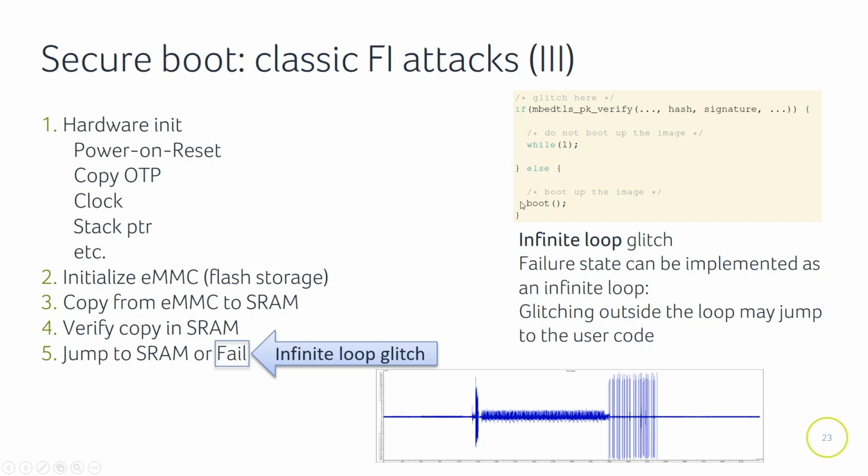We end up here. And the beauty of this attack, or this glitch, is basically that now we have infinite time. We can glitch anywhere because this is an infinite loop, so now we do not have any timing restriction. We can keep glitching, and as long as we manage to corrupt this endless while loop, we're done. We will end up in our booting code. So this is a classical attack, and it is something that has been haunting many secure boot implementations. We might still see one of these things. Make sure that you do not have this in your implementation.